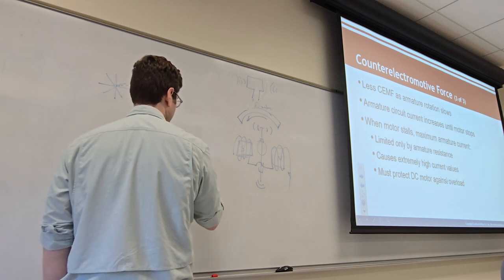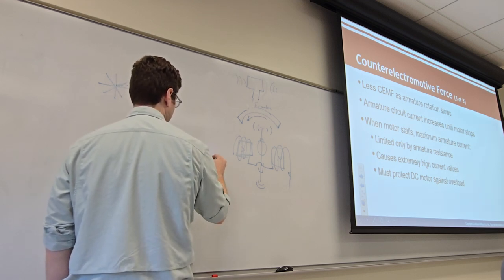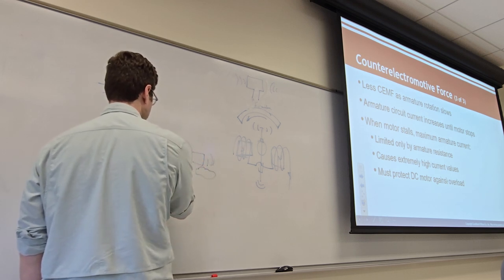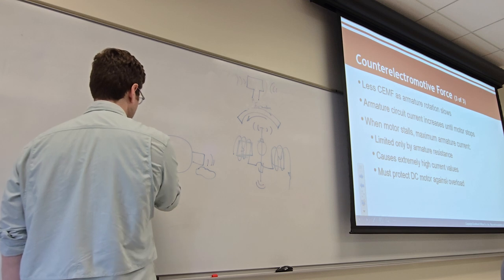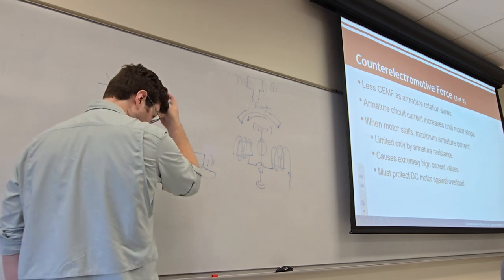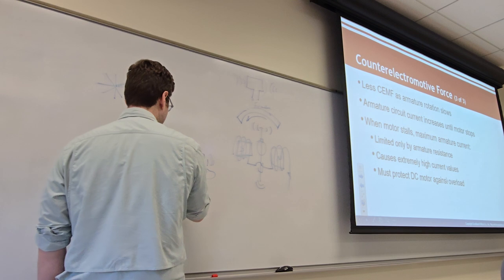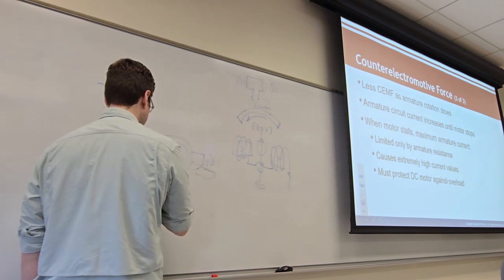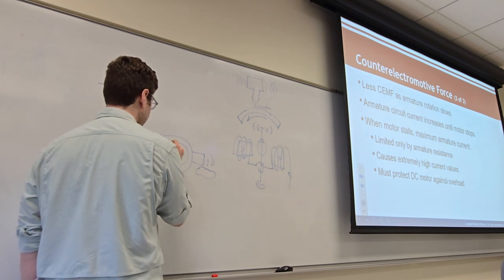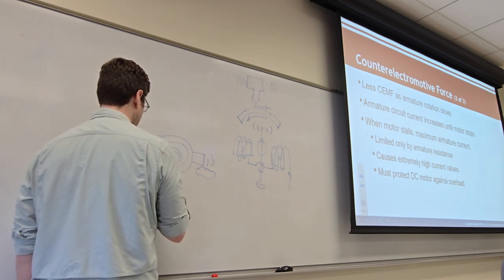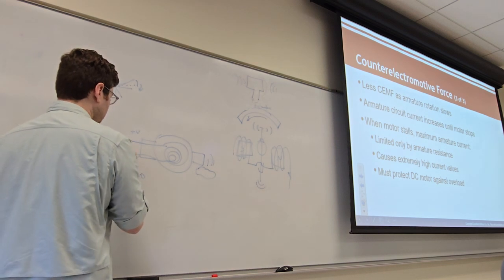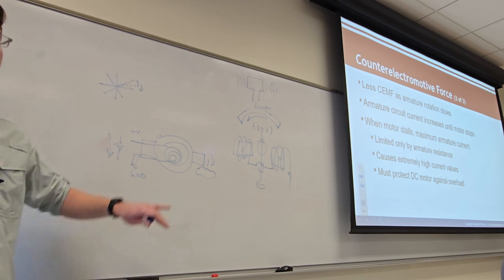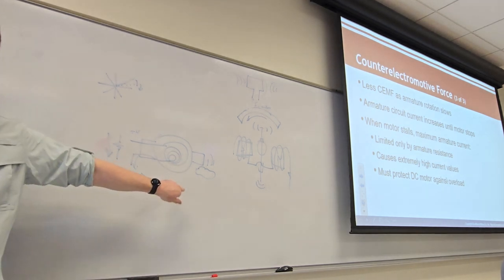If I have a motor that's turning and it hits a rock or something and can't move anymore, and I'm continually energizing that motor with my positive voltage, what happens is the motor essentially just looks like a bare piece of wire shorted between your positive supply and ground. It becomes a really low resistance resistor that you dump all that energy to straight to ground. That's why motors heat up so much when they stall.